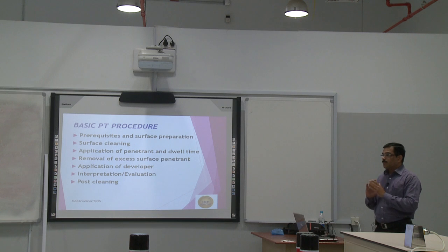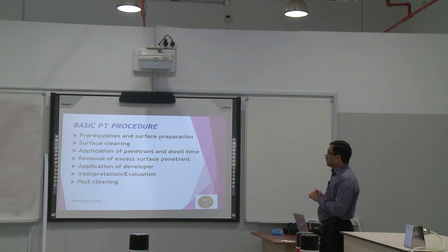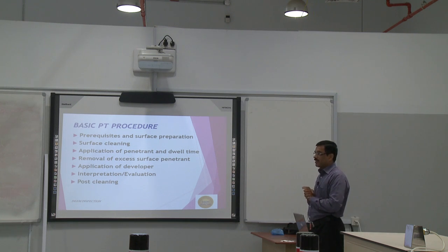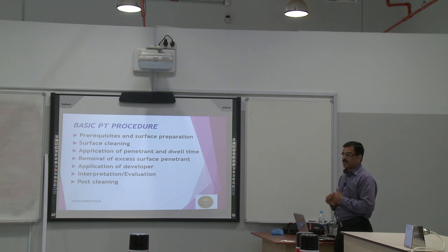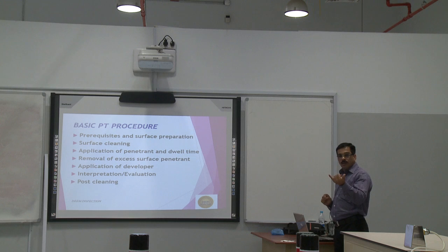These are the basic procedure steps while doing PT. The first one is prerequisite and surface preparation. Before doing the penetrant testing, surface preparation is very important, because, as already mentioned, one limitation of penetrant testing is that the defect should be open to the surface, then only we can detect it.